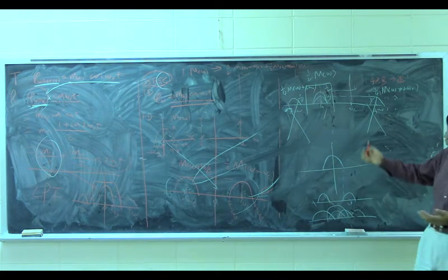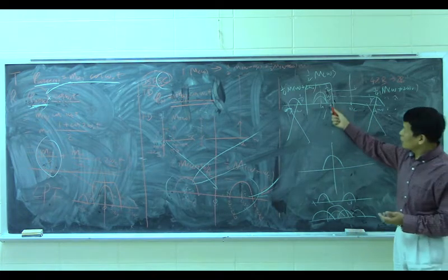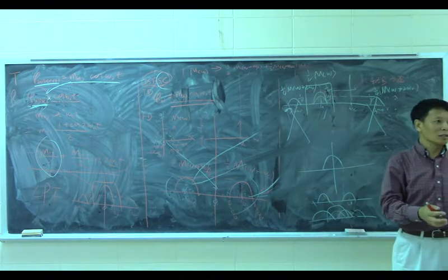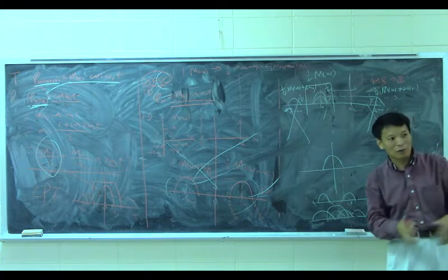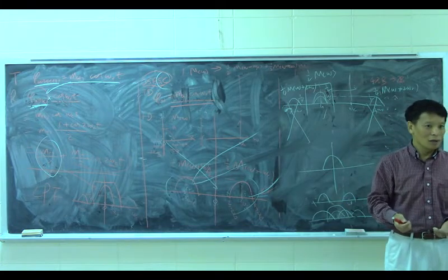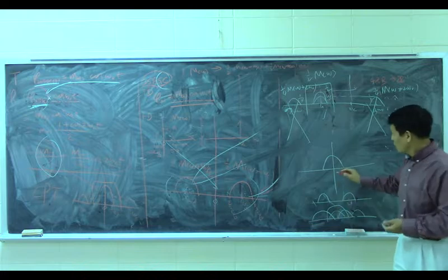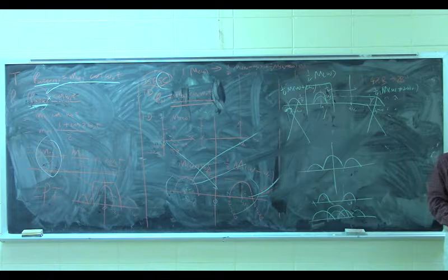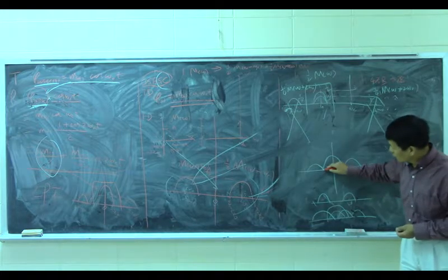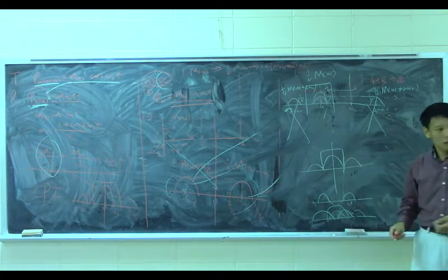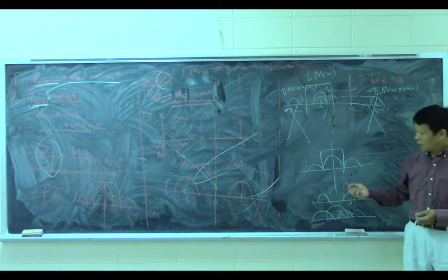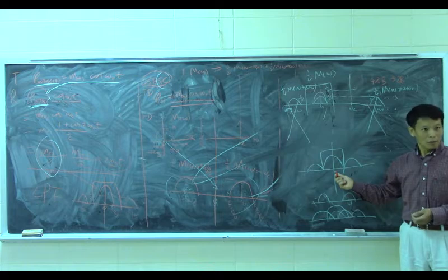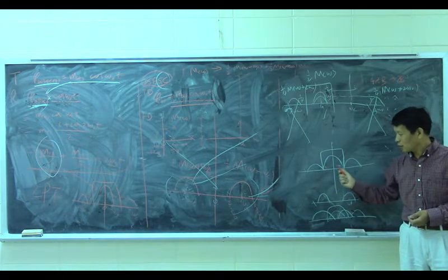You may argue, okay, if this one is larger than this one, that's okay, we understand. But why do I say we need this one to be greater than this one? If this one is equal to this, what you have is like this. Now this is what we want, right? So you just use a low pass filter, get what we want. The question is, can you make a low pass filter like this? No, you can't. You cannot make a low pass filter as a perfect window.